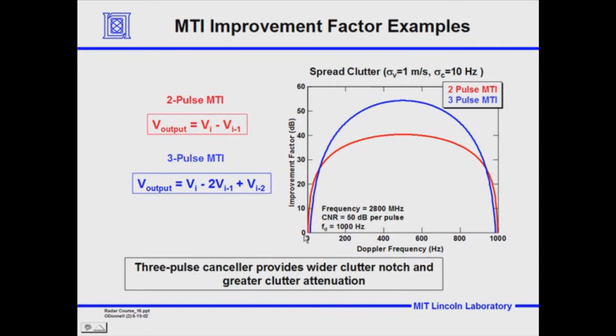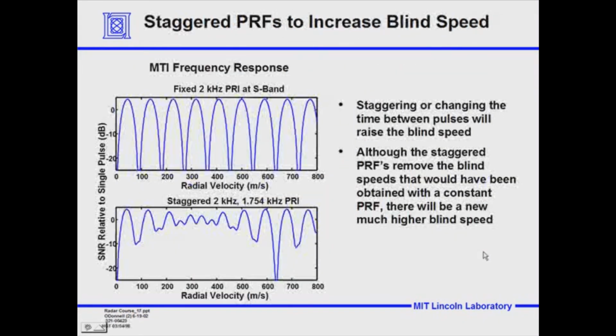These points at 1 over the PRF in sample time, if the Doppler frequencies of 1,000 hertz, which would correspond to about 120 miles an hour, and 2,000 hertz, there's a multiplicity that happens because of the sampled nature of the data. We wouldn't get good detection there. We have what's known as blind speeds. We'll talk about them later.